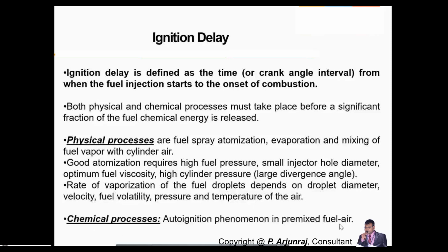The next is the chemical process, or chemical delay. The auto ignition phenomenon is going to happen in the premixed fuel and air. The chemical reaction in air and fuel will happen during the premixed stage. The delay time is going to be more, and that plays a vital role in the ignition delay.